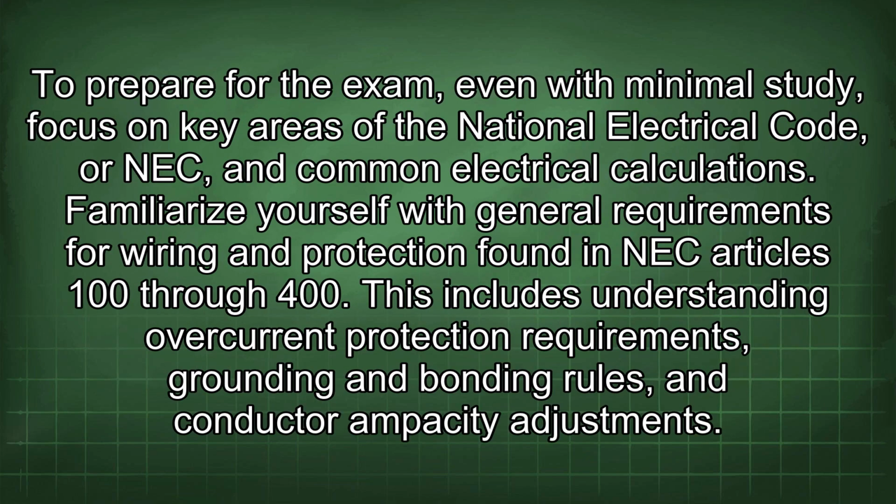To prepare for the exam, even with minimal study, focus on key areas of the National Electrical Code, or NEC, and common electrical calculations. Familiarize yourself with general requirements for wiring and protection found in NEC Articles 100 through 400. This includes understanding overcurrent protection requirements, grounding and bonding rules, and conductor ampacity adjustments.